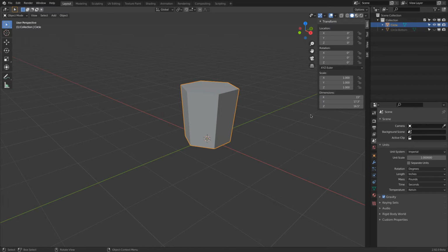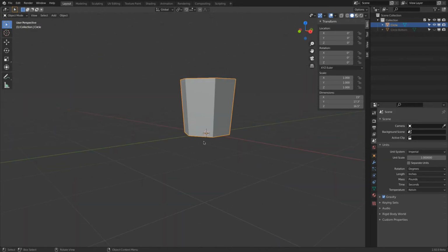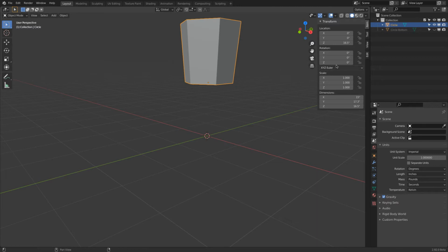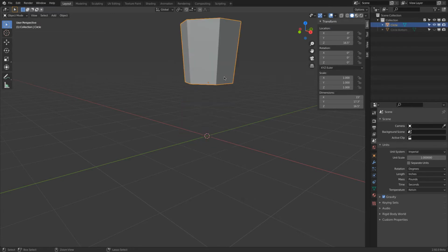The whole object has a height of 16.7. I created this from a circle, so the object center is right at the bottom, which means, Control-C, Control-V, I can move this one up. Then rotate 180 on X or Y, and Z 90. Oh, this is actually the bottom, so let's undo.